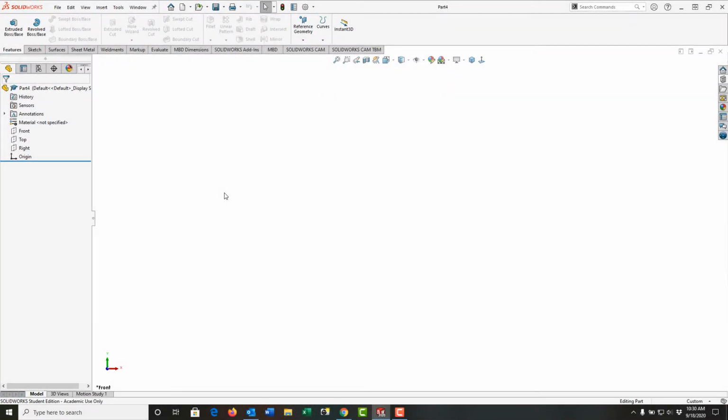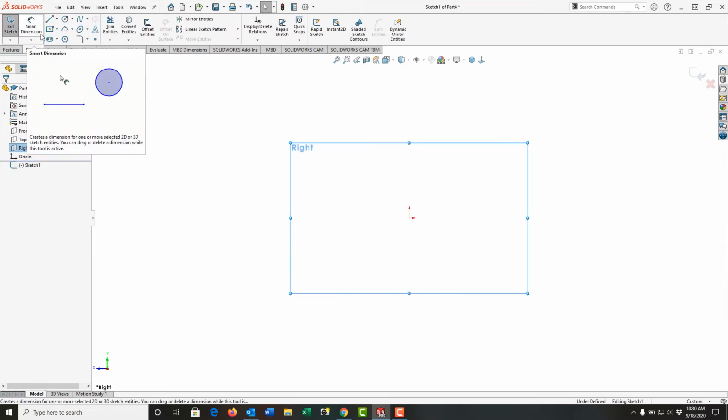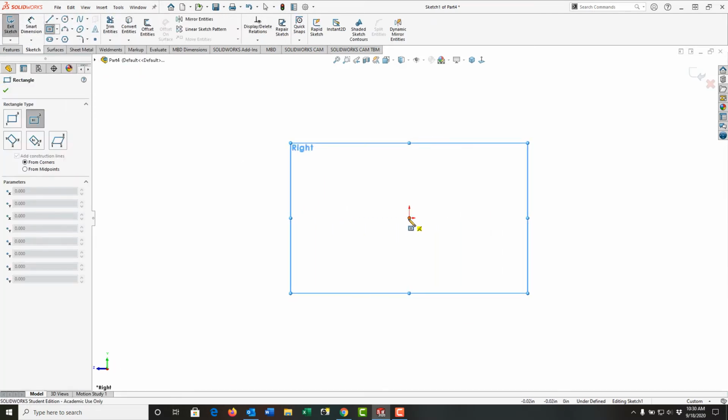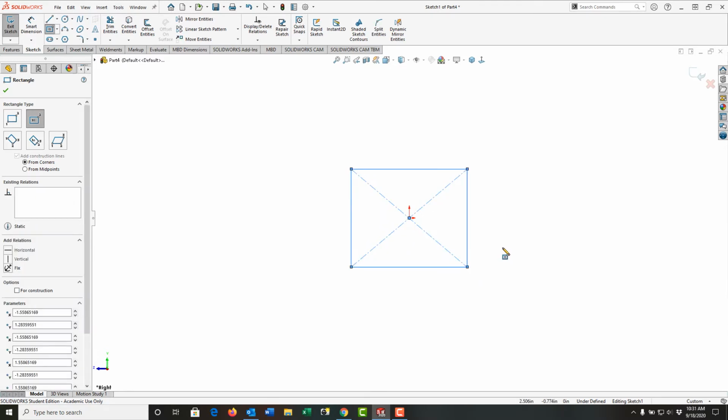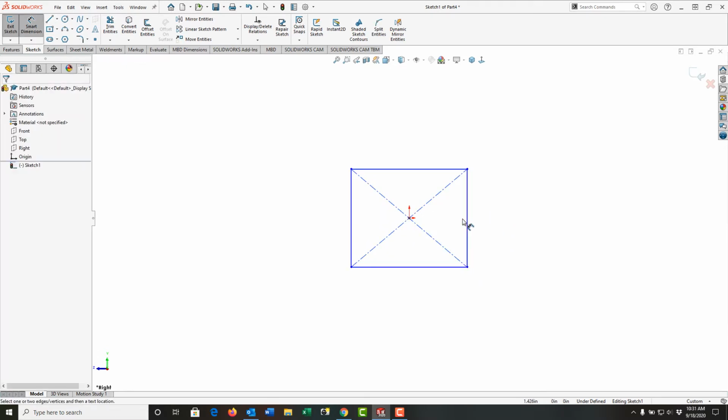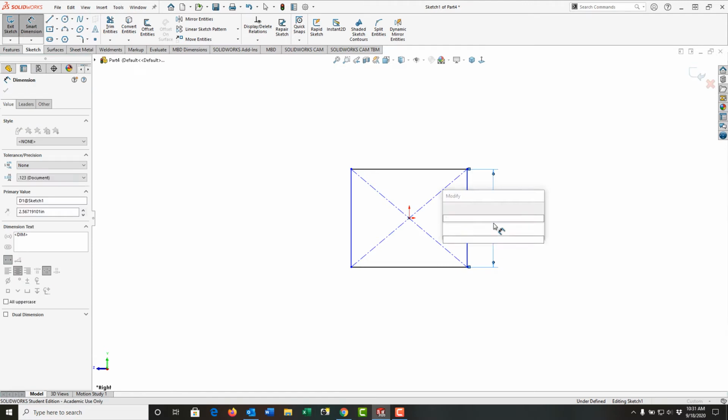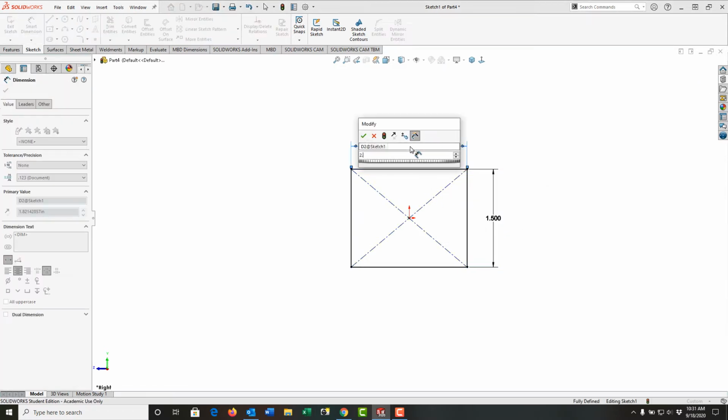In this video, I'm going to demonstrate how to make the sheet metal forming tool button with slots that starts on page 14-2 of your textbook. So first I'm going to choose the right plane and tell it I want to make an extrude boss. I'll activate center point rectangle, click on the origin, move out and click, create my rectangle. Use mouse gestures to activate dimension, and I'll dimension at 1.5 by 2.